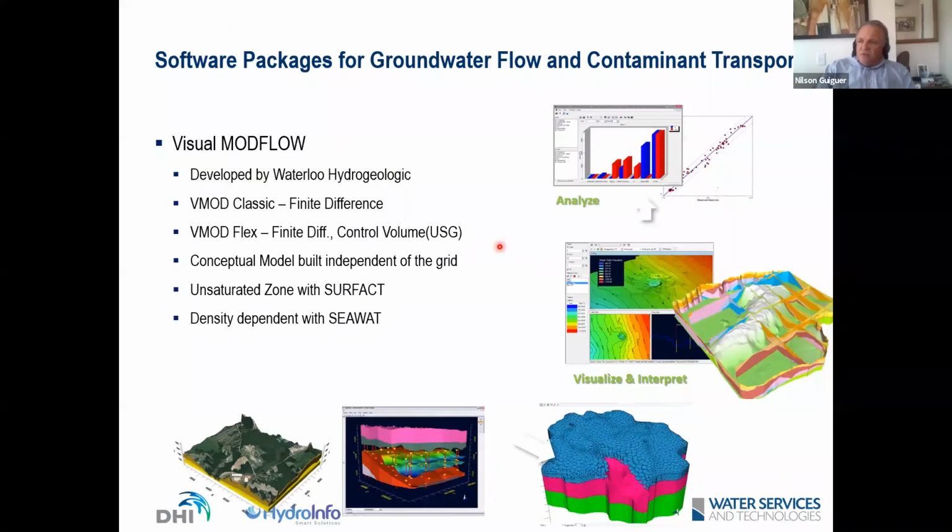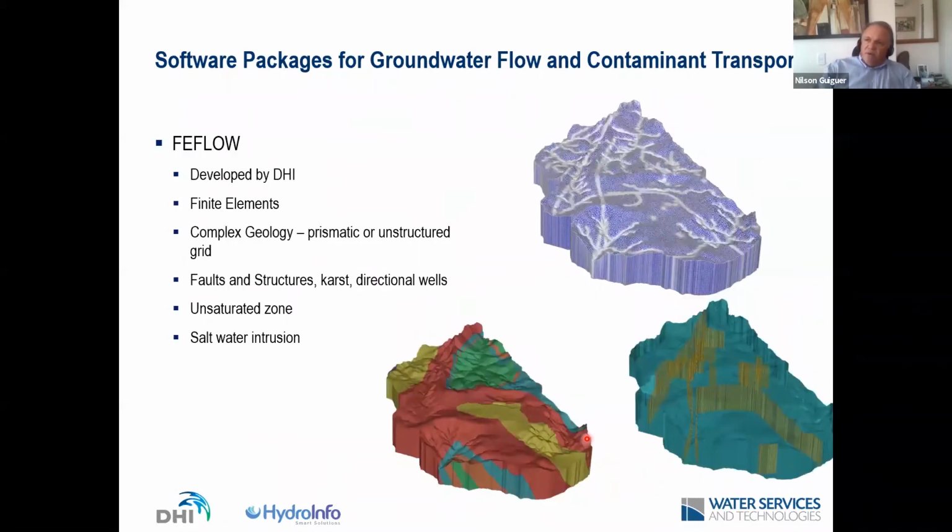Visual MODFLOW is another popular package. Visual MODFLOW Classic used to have only finite difference. Now the Flex, it has one differentiation because you can build the conceptual model right in the graphical interface of Visual MODFLOW Flex, and then it's totally grid independent. So once you have your conceptual model, you can put traditional finite difference, you can put Voronoi unstructured grid for MODFLOW. So it becomes very nice, but has the limitations that we are going to see, intrinsic of MODFLOW. We're going to see some of these limitations, which are overcome by FEFLOW.